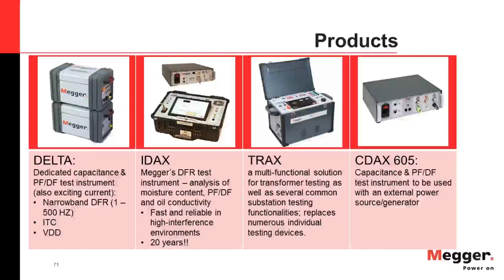Absolutely, as Jill showed at the beginning of the presentation when she was explaining the basics about the insulation. It's a capacitor, and the capacitance depends on the physical or geometrical composition of the insulation. So the area of the insulation and the separation between the 2 elements that make up the insulation are definitely going to affect the value of the capacitance.